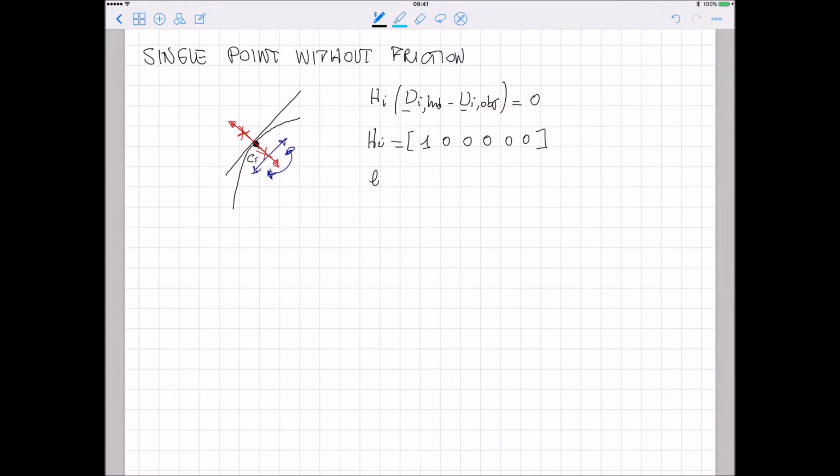and so li is 1. The dimension of our constraint is 1, because I take only one of these components and set it equal to 0, and this component is the relative motion in the direction orthogonal to the contact surfaces. So I have only one constraint. Then I will have, as we said before, only one component different from 0 of the contact branch.